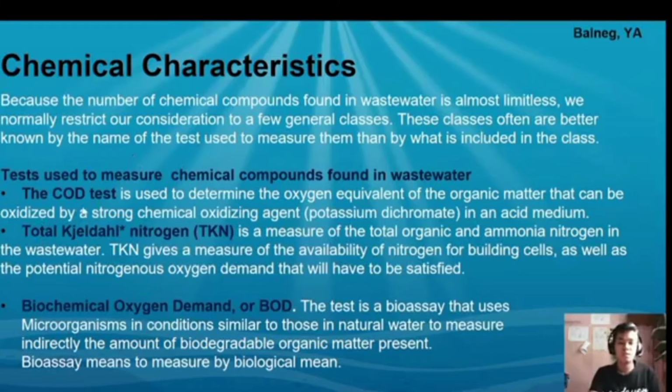One of these is the COD test, used to determine the oxygen equivalent of the organic matter; the total nitrogen, to measure the total organic and ammonia nitrogen in the wastewater; and the biochemical oxygen demand, the measurement used to measure the amount of biodegradable organic matter present in the wastewater. As I've said, our wastewater contains chemicals, especially the septic sewage wastewater, because it's part of our diet.